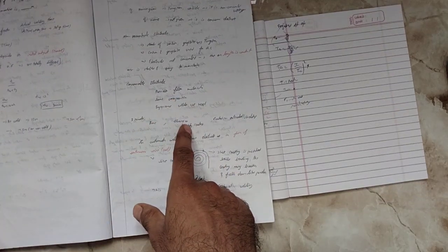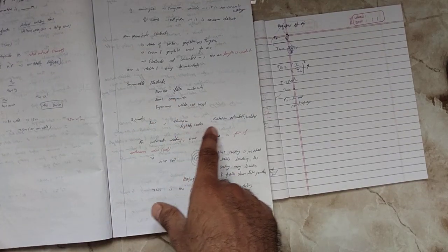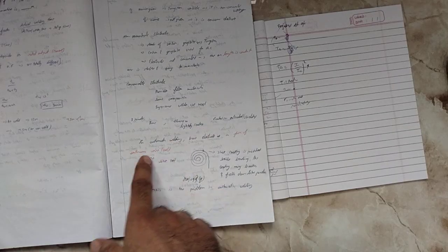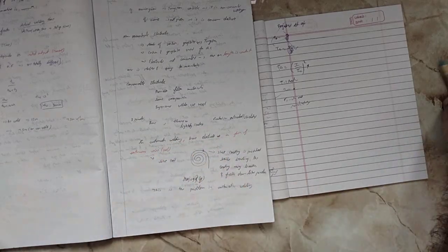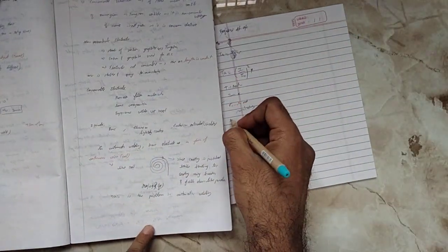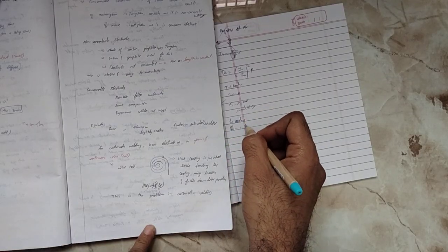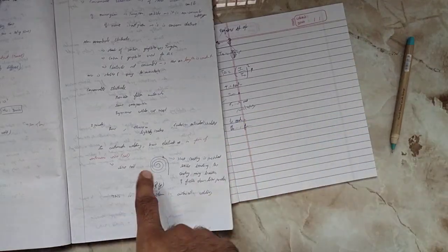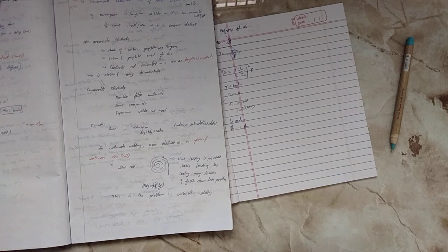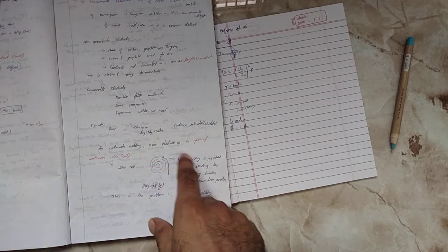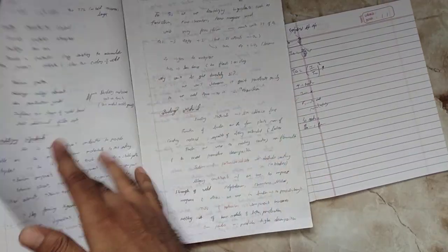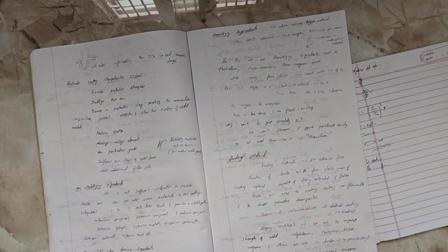So there are three kinds: bare, fluxed or lightly coated, and extruded. For automatic welding, the bare electrode is in the form of continuous wire. Since the coating is provided, while bending the coating may break and fall. Because it is continuous, it may be a problem, so this is a problem in automatic welding. The next thing, just wait one sec.